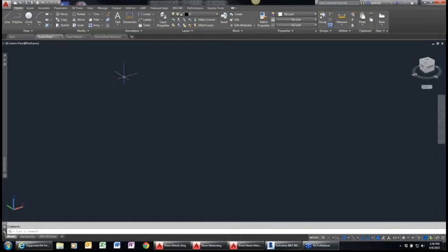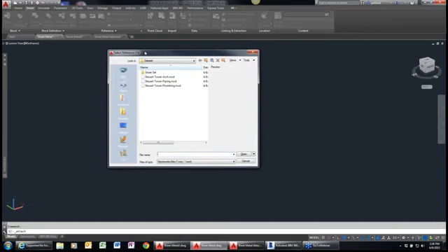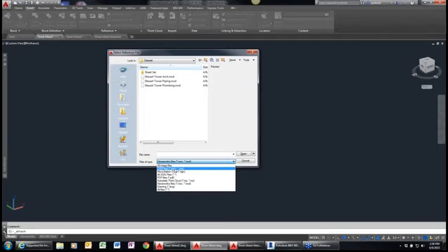And there's really been no good way to do that other than exporting DWGs from Revit into AutoCAD. But with 2016, we actually have a new set of tools where you can go in and use the XREF tools, the attach tools, and in addition to the standard DWG files and things like that, you can now actually import a Navisworks file.